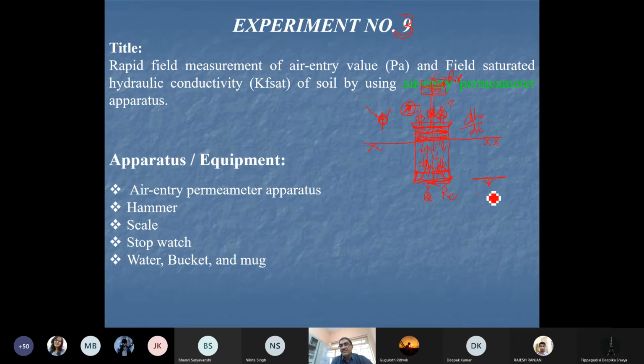So what we are simply taking is 0.5, or half, of the air entry pressure at the top of this soil as the actual pressure head at the bottom of this front. This front is moving because of the pressure created by this water initially.